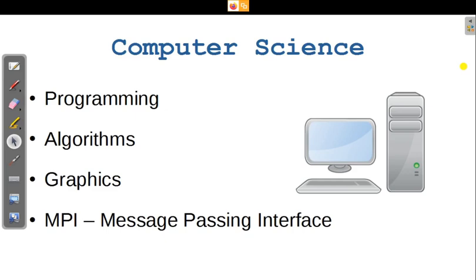So this message passing interface will say that, okay, I have a small domain. This has this boundary condition. Okay, you have your domain, you have this boundary condition, you solve. So once the first iteration is done, the processors will communicate among themselves that we are done with the first iteration. Shall we go ahead with the second iteration? Okay, then all processors will go ahead with the second iteration. That's how this message passing interface helps.